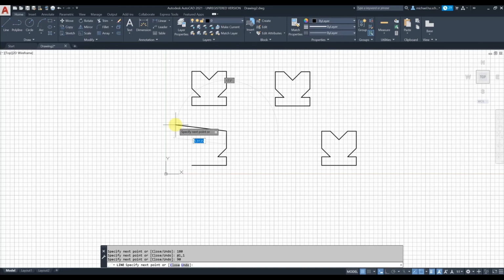Next we're gonna do so the length will be 1, the angle 180 degrees. Then we're gonna use Cartesian coordinate here. So that will be -1, -1, right? So we're gonna do Cartesian here as well. -1, +1. And here we're gonna use polar. So length is 1, tab key for the angle 180 degrees, right?